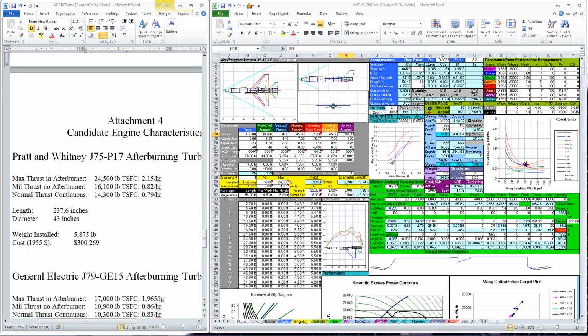We can actually reduce maybe to 75 square feet, 76 square feet. Okay, we've got enough CN beta, we've got a good ratio of CN beta to CL beta. I think this is going to be a pretty nice flying airplane. We're just a little light. Let's go 35,000 so that we're still a couple hundred pounds short. Let's go 35.5. As the airplane gets heavier, then it burns more gas, so that's a problem. And it looks like we meet all our constraints.